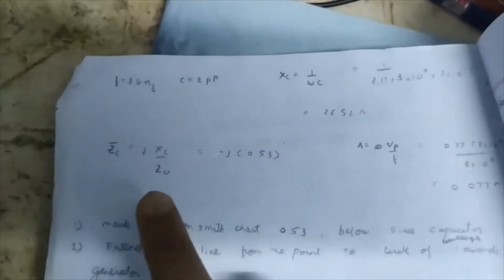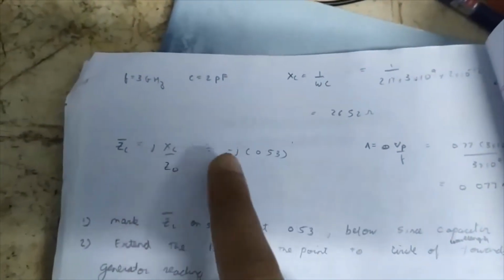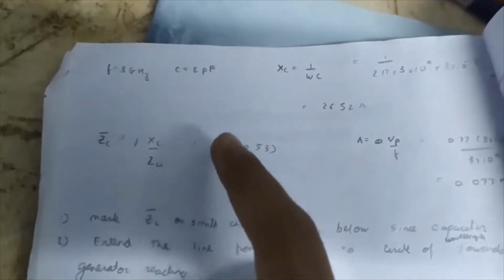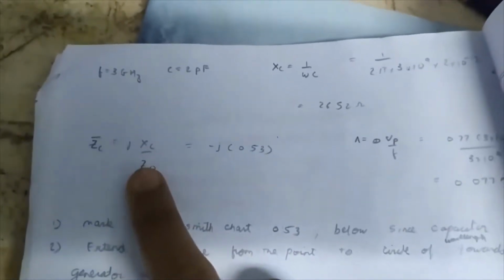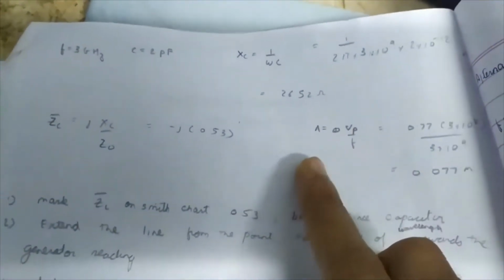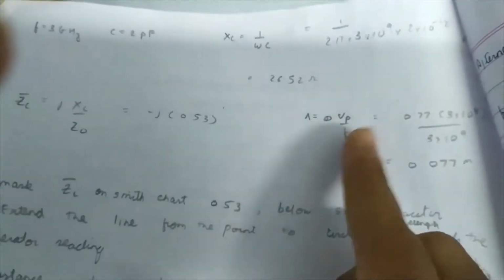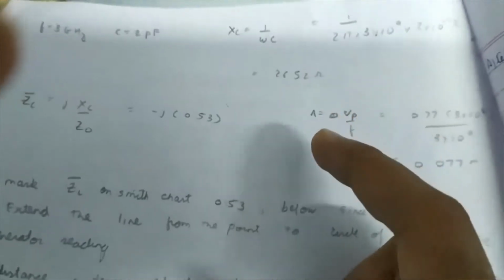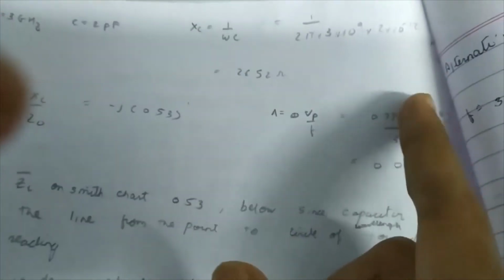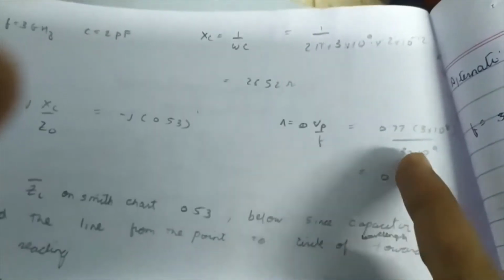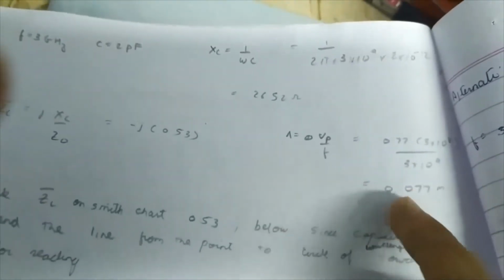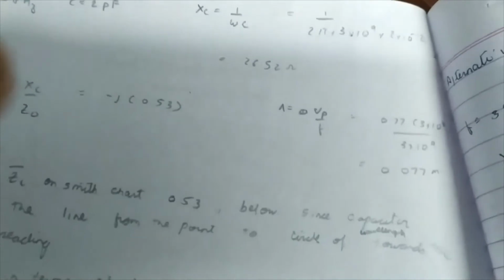Then we have to normalize the impedance that we have got with the characteristic impedance, which is 50 ohm. We can also find the wavelength. At last we have to find the distance in terms of wavelength, so we need to multiply with the wavelength. The velocity is 77% of the speed of light divided by the frequency of operation, so we get the wavelength as 0.007